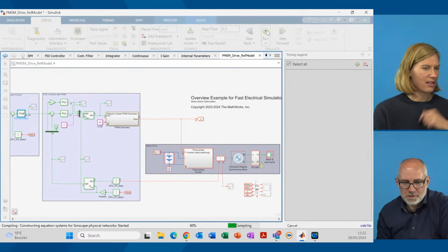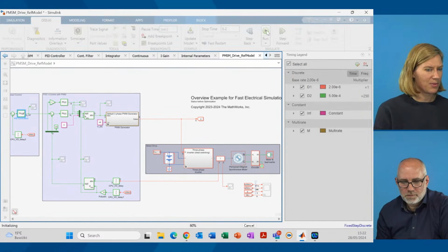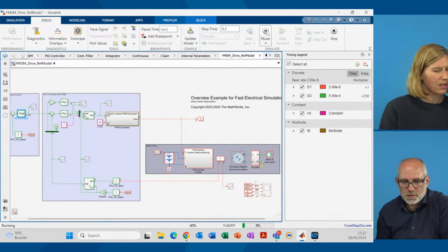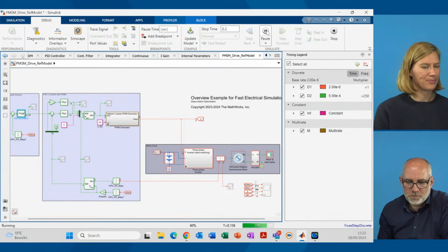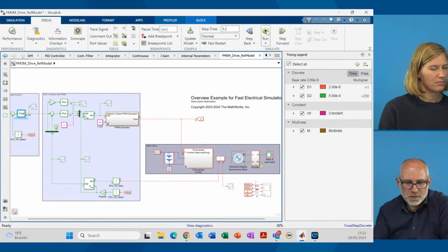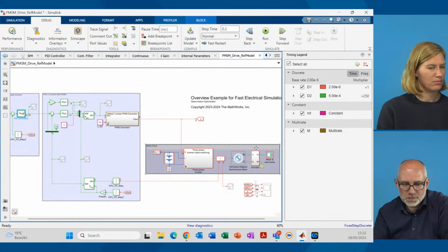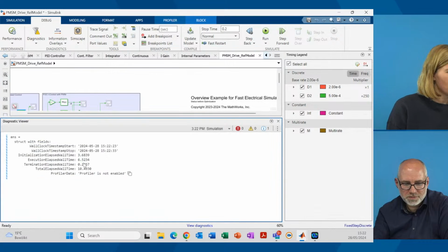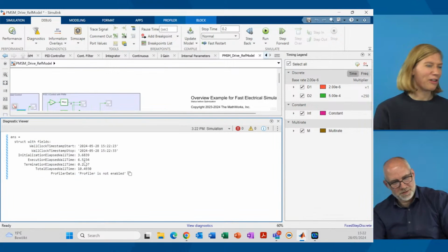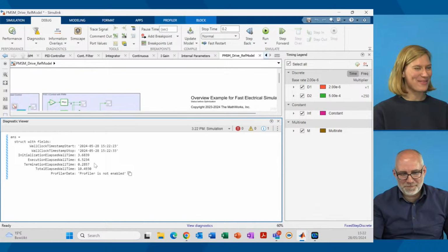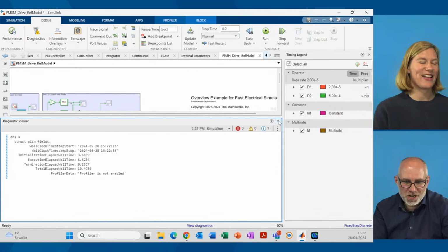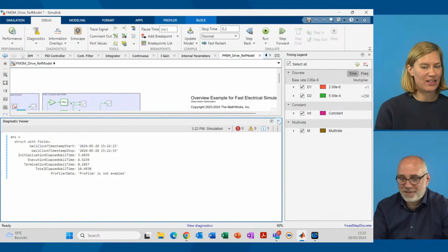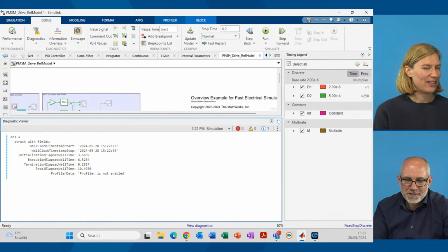So we're still running the Simscape model at fixed step, and the global solver is still at fixed step. We had 10 seconds before, so just discretizing the blocks. Where are we now? Oh, 6.4. That's not so little actually. It's about 40%. That's a lot. So you see, small changes can change your life here quite a lot.